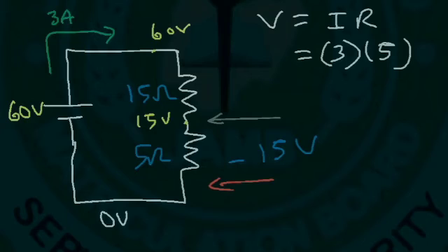Now, as we said before, the ammeter requires a low internal resistance to accurately measure the current that flows in a circuit. Now the voltmeter requires a very high resistance to accurately measure the voltage across an element. Let's understand why. Let's use the concept of internal resistance to figure this out. So let's say we have a battery and we have the internal resistance of the battery, and then we have this external resistance.